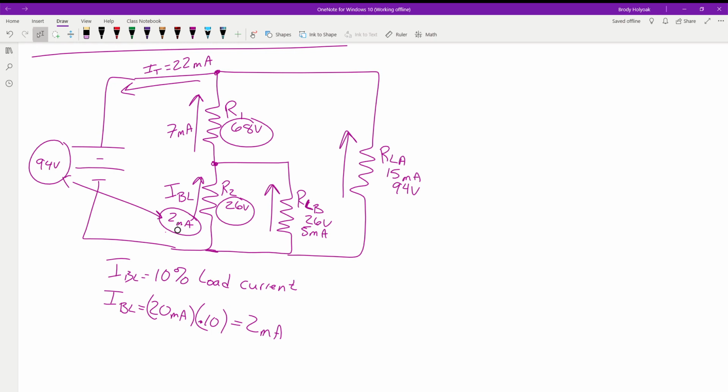It doesn't matter what kind of power supply you use. It just matters how much voltage you get. Remember at the beginning of the semester when we were going through to find out if these power supplies could be series dependent or parallel? That's what it is. It allows you to connect it up in series or parallel. Because in parallel, you're going to be drawing more current. In series, you're going to be spitting out more voltage. So it has different internal wirings to help provide either the current or the voltage for what you need.